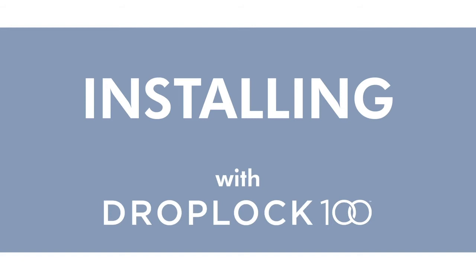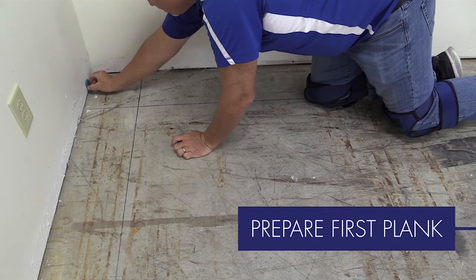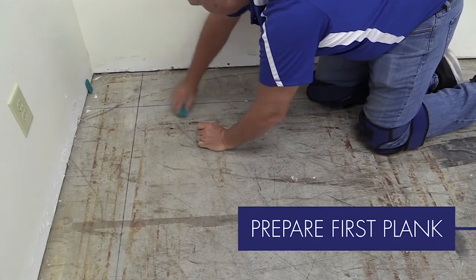Install Engage Genesis or Engage Inception with Drop Block 100 by first determining your starting wall and setting spacers to create the required expansion space between the planks and the wall. These will remain in place until installation is complete. Installation will begin from left to right, beginning in the left corner with the long groove edge facing you and the tongue side facing the wall. Position the first plank against the spacer a few inches from the starting wall.